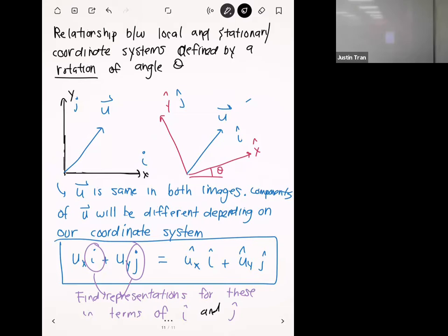And then the displacement, the difference from that versus fixed means that it's not moving in a certain direction, right? But it can still perform. Yes. And so with the displacement constraint, we're basically preventing the bridge from displacing in the y direction, which is this direction.